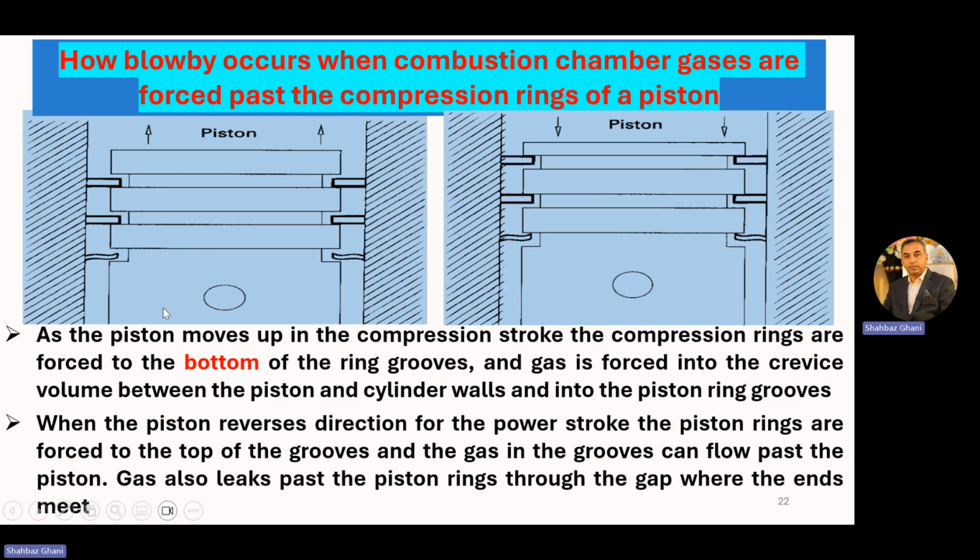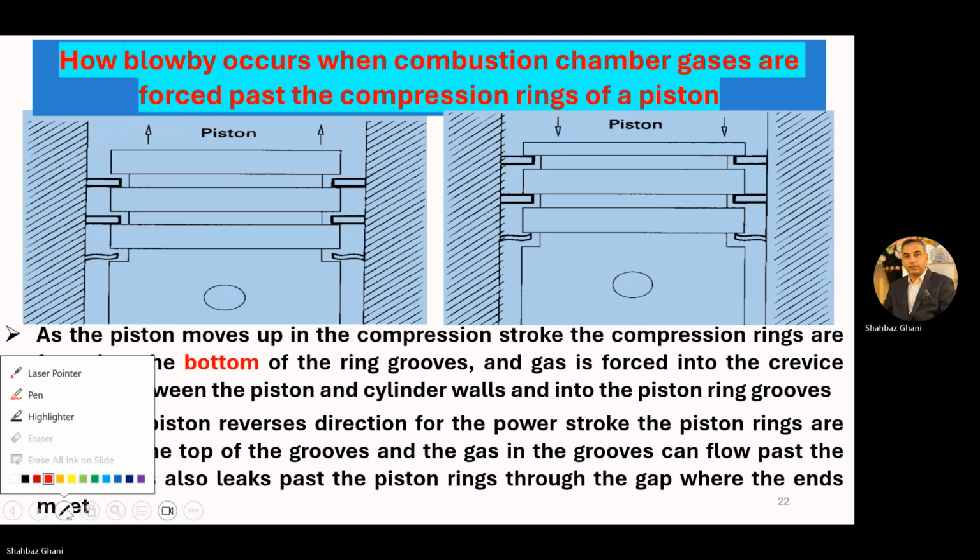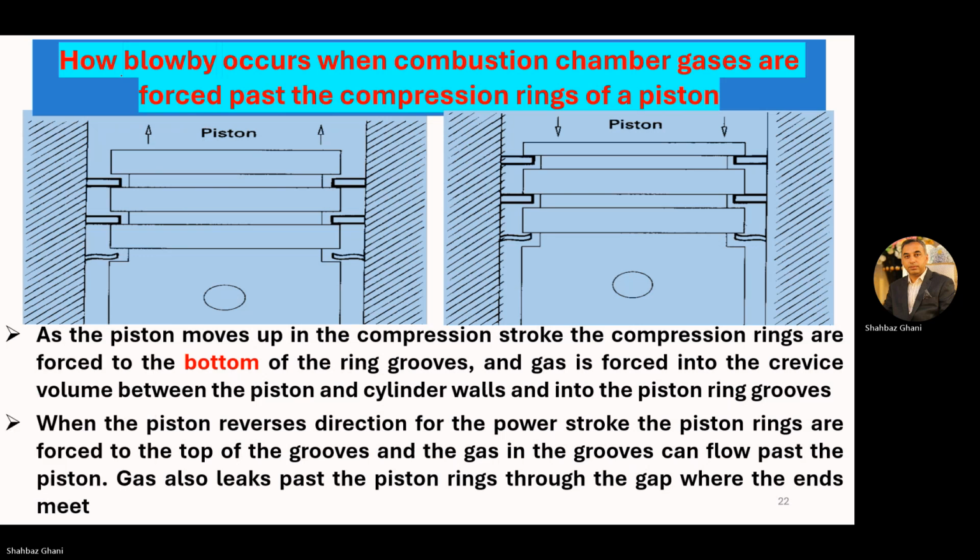Now the piston is moving from BDC to TDC. At that time, the rings will rest on the lower surface of the piston grooves. The combustion gases will come into this area.